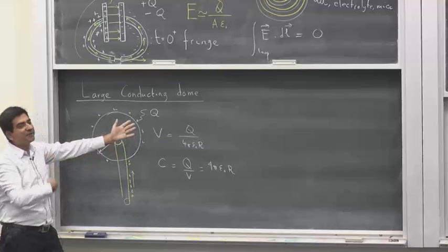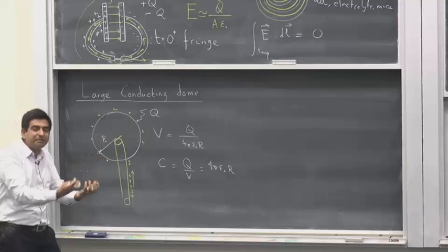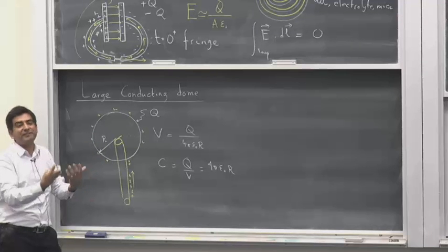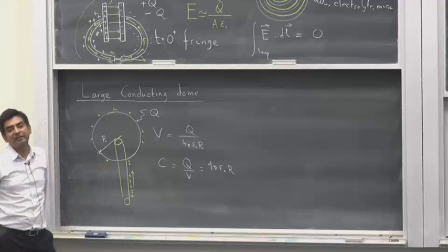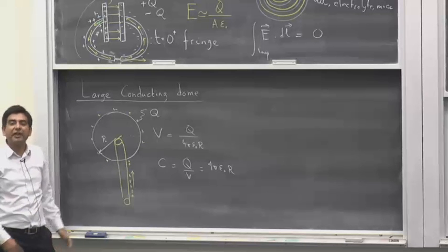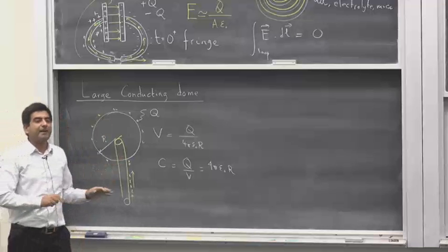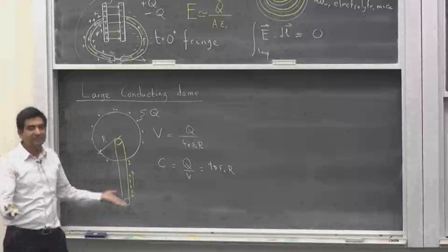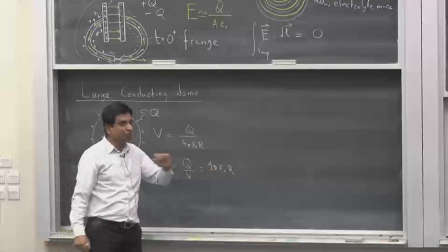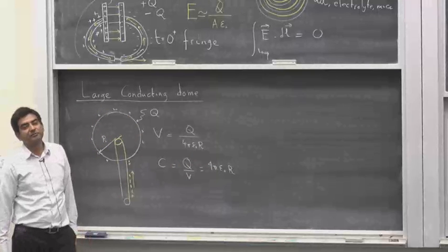So that charge per unit time gives me a current that is less than my perceptible threshold of sensation of feeling a current. It's less than, say, 1 milliamp perhaps. So I cannot feel that current. So even though it's a big voltage, it's a benign experiment because the capacitance is so small because of this epsilon naught here that it does not carry a sufficient amount of charge.